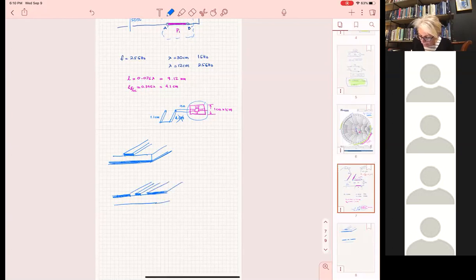In a coplanar waveguide, when you look from the top, it looks like 3 metals: the center one, and then 2 larger metals. Theoretically, they were infinite, but of course, nobody is going to print an infinite metal because it creates other kinds of problems. So usually, the 2 outer metals are finite, but bigger than the center one. It looks like this.